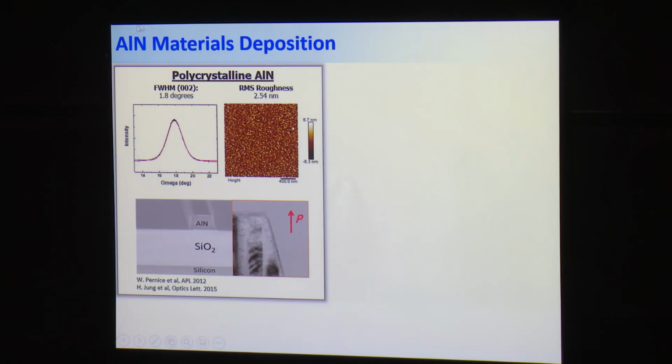There are two different methods we use to fabricate aluminum nitride thin films in the lab. The first approach is just like a MEMS approach: you sputter aluminum nitride on your substrate. Normally in MEMS, you sputter on metals. About 10 years ago, a student decided to sputter directly on oxide. Oxide is an amorphous substrate, and magically after sputtering, the domains of aluminum nitride all line up. The C-axes all line up. This is just thermodynamics at play. They align within 2 degrees.